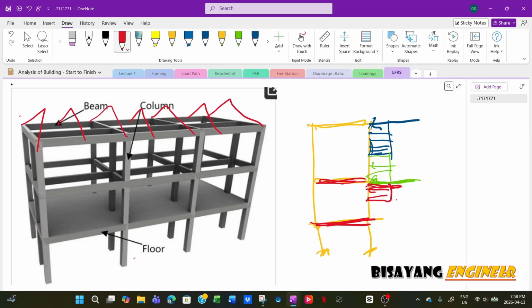If you are not using the roof as a diaphragm, then he said he analyzed the truss as an independent system. So whatever horizontal reaction you get from your truss, whatever the result is, apply that to the model. Now you have to make sure that you apply the load at the right location.